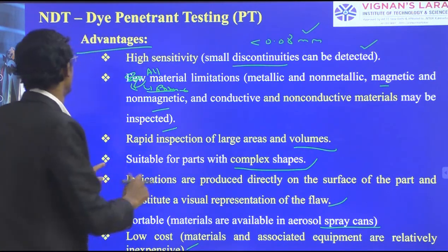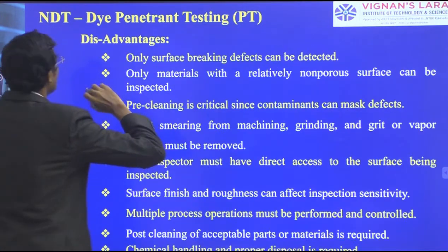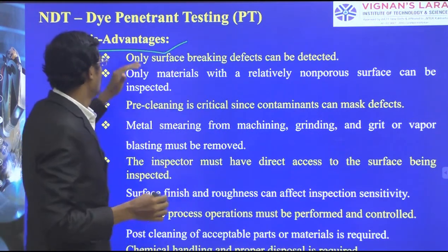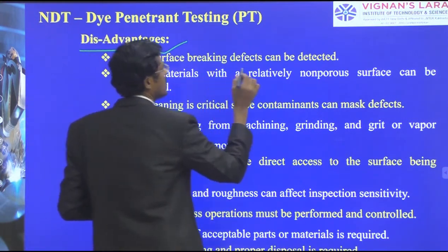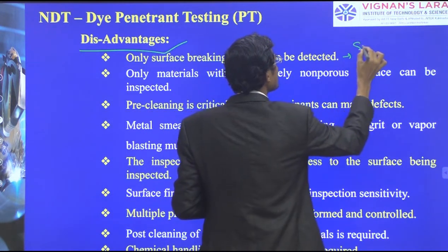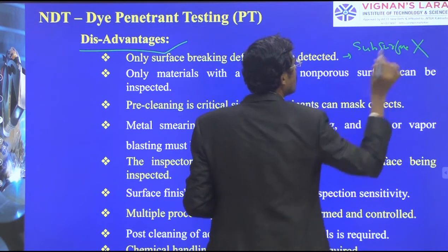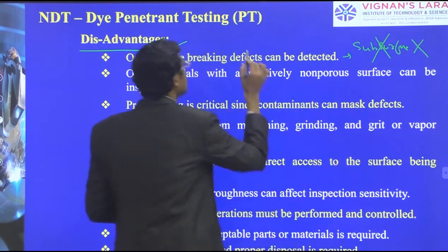It takes a short time. Even though it has some good advantages, a few disadvantages are available. Only surface breaking defects can be detected. It means subsurface defects are not possible, and also porous materials are not possible.